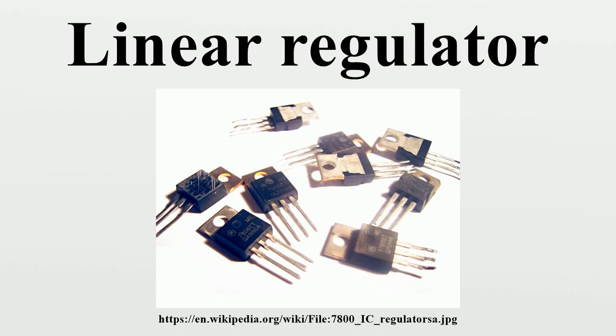Once R1 has been calculated, removing R2 will allow the full load current through the diode and may exceed the diode's maximum current rating, thereby damaging it. The regulation of this circuit is also not very good because the Zener current will vary inversely depending on the load current. In some designs, the Zener diode may be replaced with another similarly functioning device, especially in an ultra-low voltage scenario, like several normal diodes or LEDs in series.